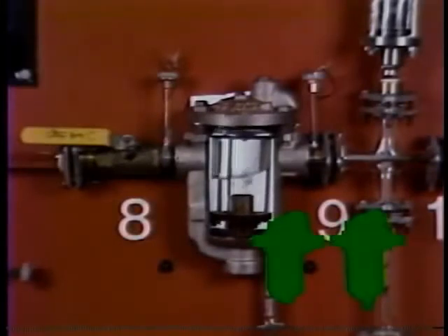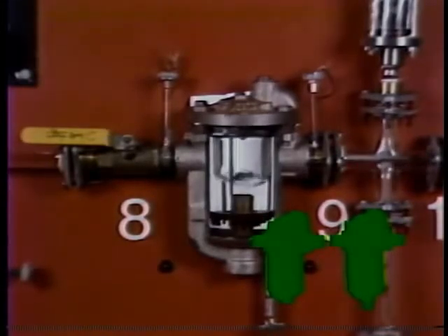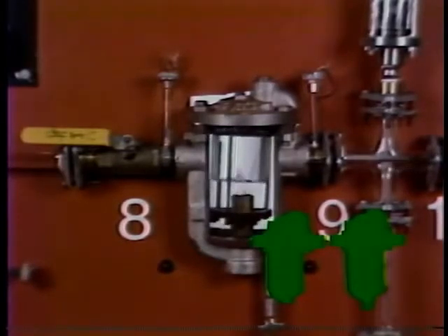Obviously, all of the other requirements we've spoken of contribute to the overall life of the trap, along with the materials chosen for the trap and the care taken in its design and assembly. Both the IB and DC have excellent service life. They have low initial steam loss and respond favorably under the conditions we've looked at. Although the DC discharges some live steam mixed with the air in order to purge non-condensables, it handles large air loads better than the IB.